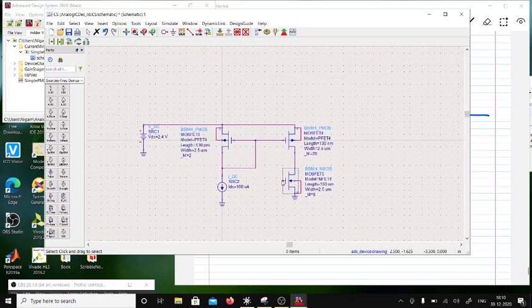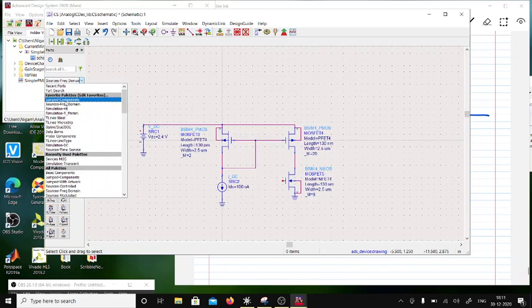Now first I have to find out what the bias should be. The bias would be V overdrive plus VT. The question is, what is V overdrive? You can compute the V overdrive with the current. Actually, if we have a current and the size, we know the V overdrive, but this is an analysis. Synthesis is the reverse of that problem. So let's first do an analysis and then I'll tell you the synthesis part.